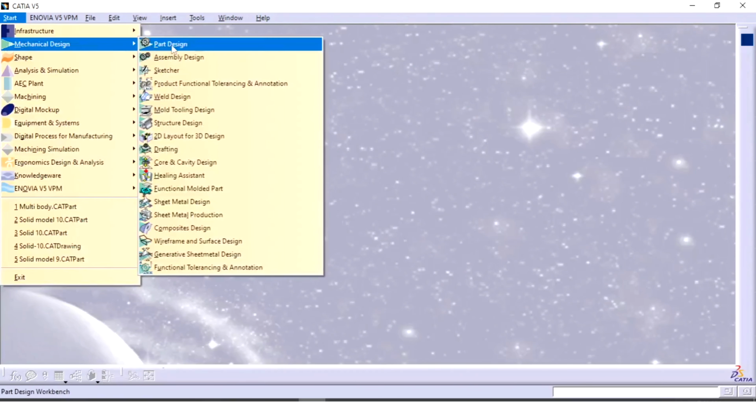And I want to remove a pocket from here. We can do it using the pocket tool, but we will go with the Boolean operation remove. For that, insert a new body. And in this body, I will need another plane which is of 10 mm offset.